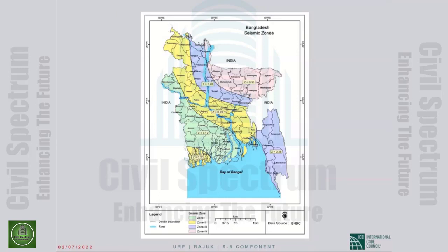And they also design a building that can withstand the design earthquake with the infill all gone. Both ways, the structure should be able to withstand the earthquake. So the specific answer is the infill initially contributes to stiffness, but the contribution goes away when the infill is damaged in an earthquake.